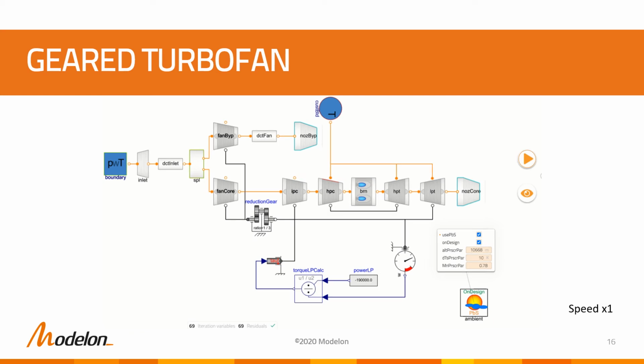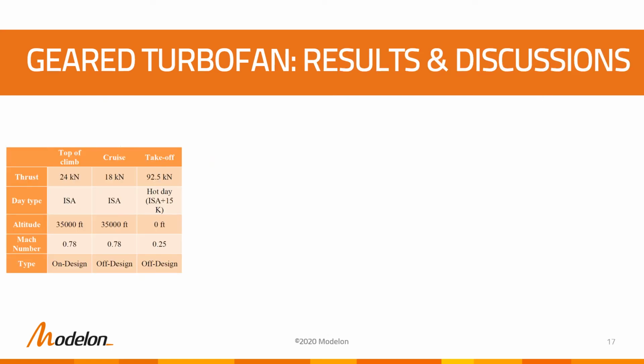Let's focus on performance and robustness. The model is compiled. We will now simulate the on-design mode. Switch to the off-design mode by unclicking the on-design parameter, simulate again, but without recompiling, reusing the sizing from the on-design mode. In both modes, simulation was fast and convergence was reached. To keep the demonstration simple and quick, we had already parameterized the model based on the following table.